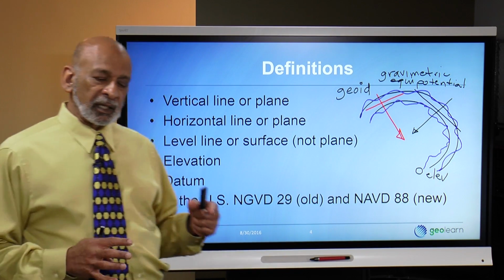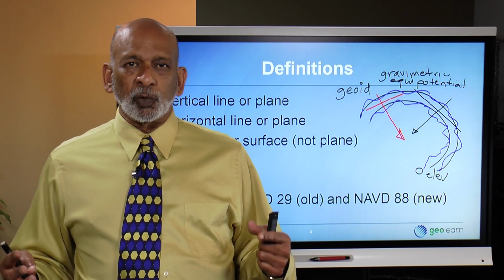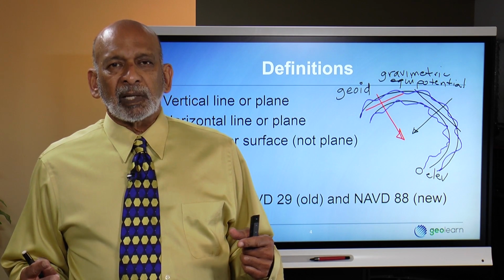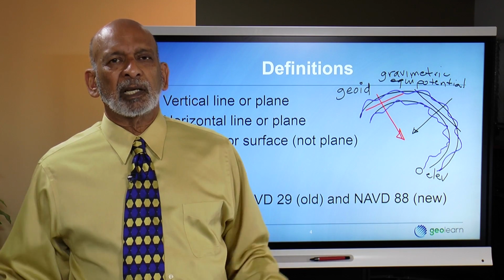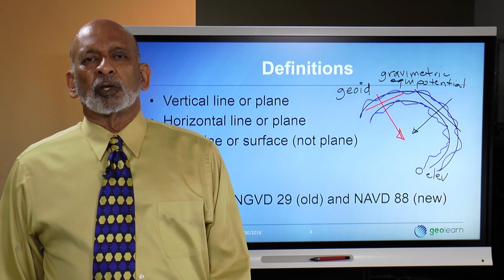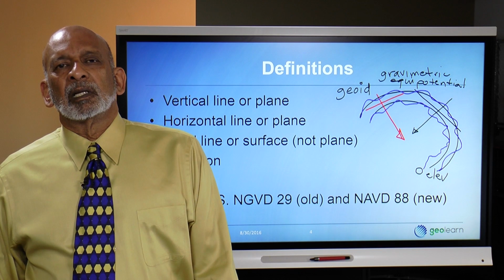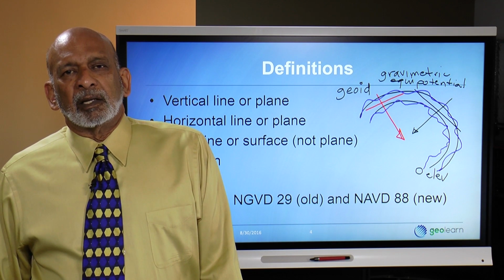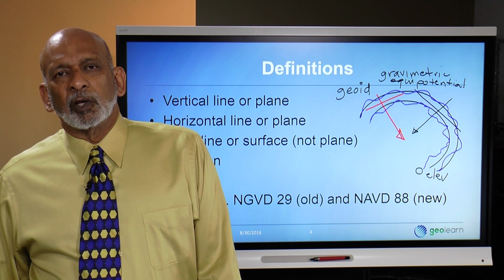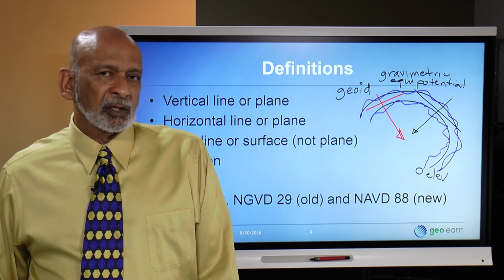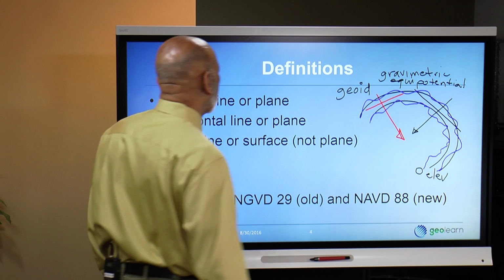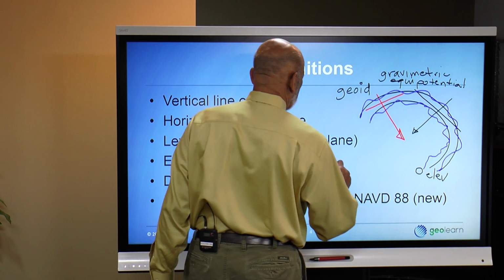And in the old days, every country would have its own definition of sea level. I think the United States and Canada actually shared a common basis, and basically what they did was they took a whole bunch of stations along the Atlantic coast, the Gulf Coast, and the Pacific coast and measured sea level for 19 years and change. It's what's referred to as the metonic cycle.